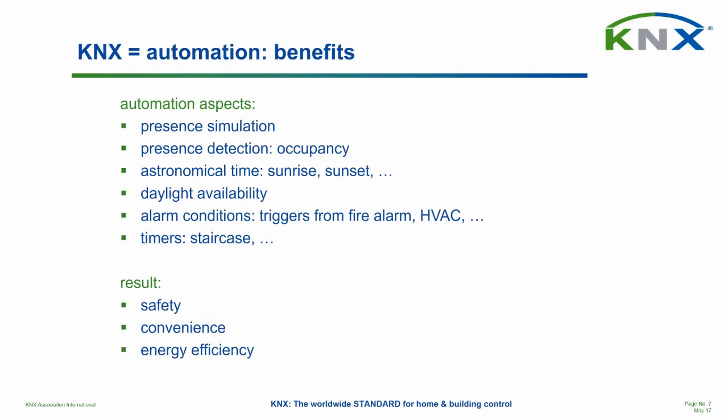We can also include in the automation of any KNX function, and specifically for lighting, the astronomical time, so that we can take into account sunrise, sunset, etc. Daylight availability, alarm conditions, so triggers could come from fire alarm or HVAC that then have an influence on lighting.